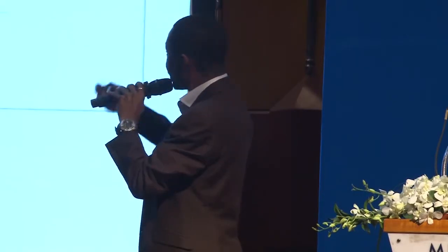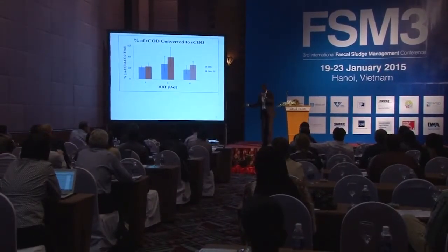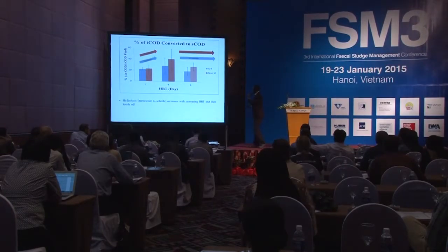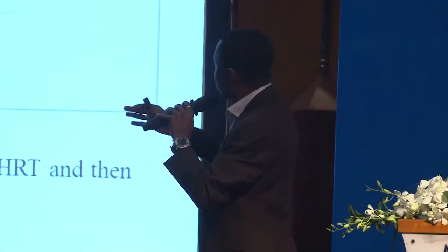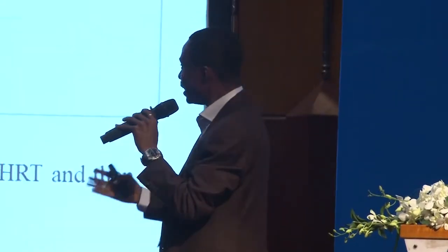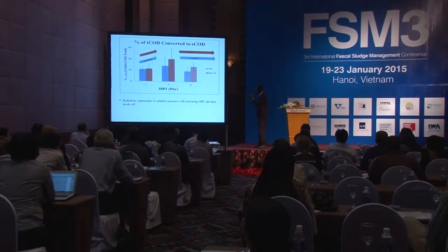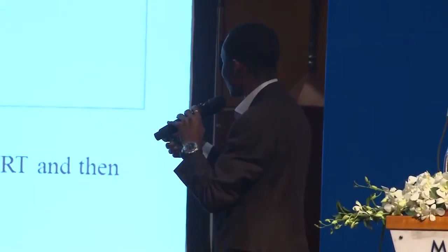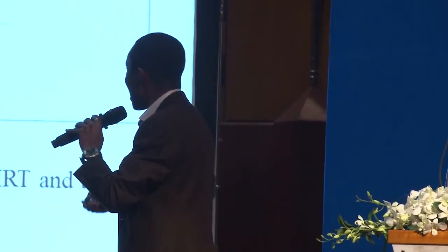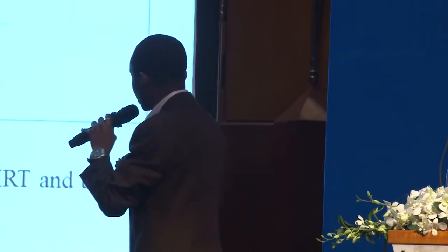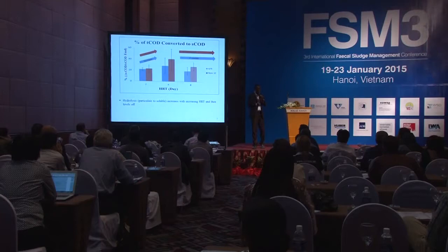This first slide on the results shows the conversion of total COD to soluble COD. This is an expression of hydrolysis. In looking at the step feed and non-step feed, we are also looking at HRT. So two things in mind: step feed and non-step feed reactor configurations, and secondly, hydraulic retention time. First and foremost, what we realize is that hydrolysis increases with increasing HRT. Statistically, that is what we realize. At both 2-day and 4-day HRT, we have hydrolysis increasing, and then it levels off for both the step feed and the non-step feed reactor configurations.